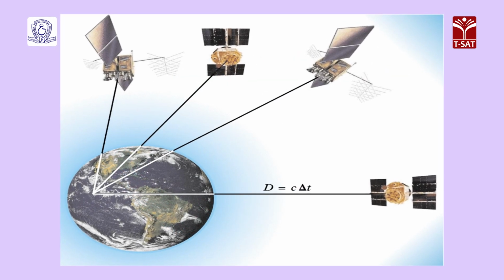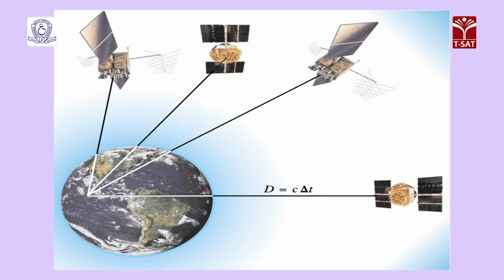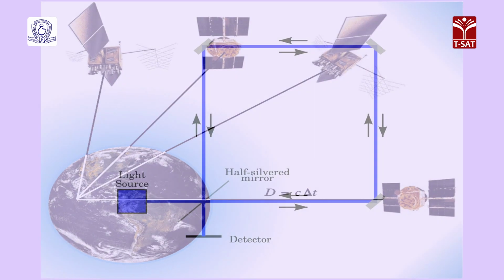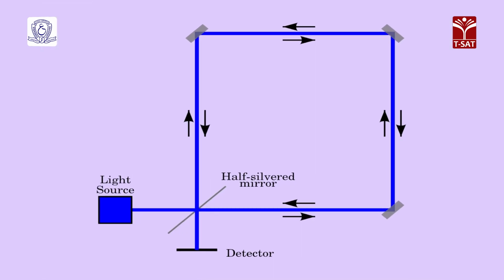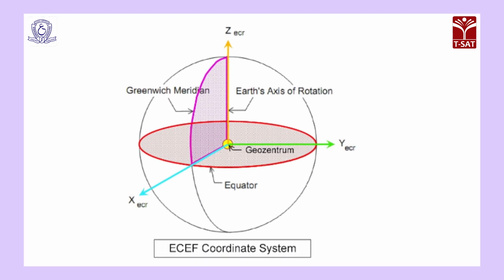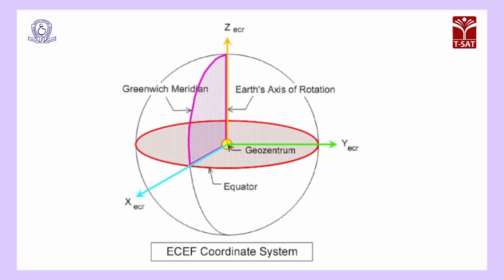Due to rotation of the earth during the time of signal transmission, a relativistic error is introduced, known as the Sagnac effect. When computations for the satellite position are made in an ECEF coordinate system, during the propagation time of the SV signal transmission, a clock on the surface of the earth will experience a finite rotation with respect to an ECI coordinate system.